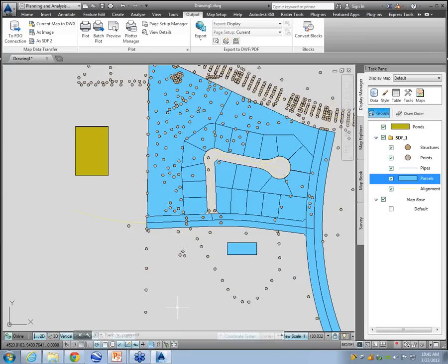I'm connected to FDO. There is absolutely nothing in this drawing that somebody with plain AutoCAD or AutoCAD LT can see, or even AutoCAD Architecture. So FDO is visible to only people with the FDO tool sets, meaning AutoCAD Map or Civil 3D. Okay? So these don't even come in as proxies. I mean, that's the problem. These don't even come in as proxies. So there's nothing going to be visible there.